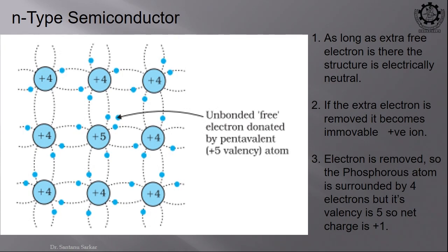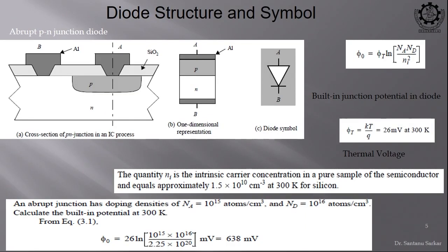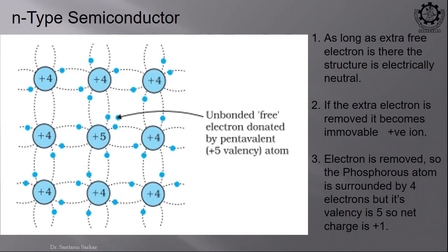On top of that, if the temperature is increased, collision is increased, and other free electrons will be generated. Also, if temperature is increased, some covalent bonds may break and a few other free electrons can join, right. So, these are the reasons that at higher temperature we have more free carriers. Okay, these are the basic things of N type and P type semiconductor structure.